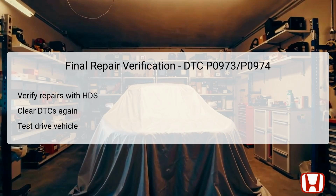After all necessary repairs have been made in response to the DTC P0973 and P0974 codes, it is crucial to verify the effectiveness of the repairs. Begin this process by reconnecting the TCM connectors and then using the Honda Diagnostic System HDS to clear any DTCs present in the system. This step ensures that any previous errors are removed and allows the system to reset for fresh diagnostics.